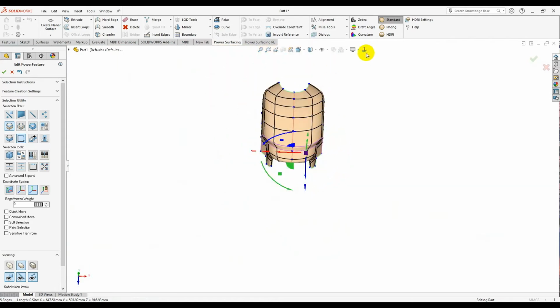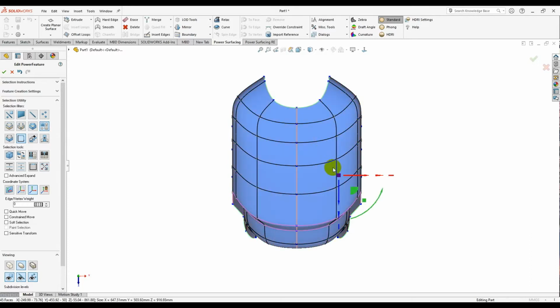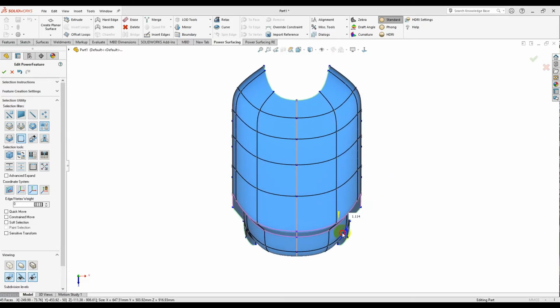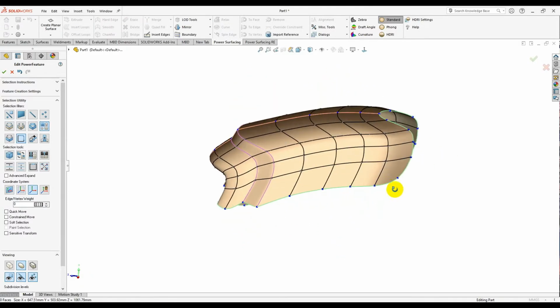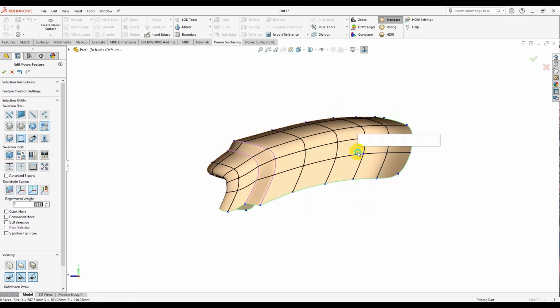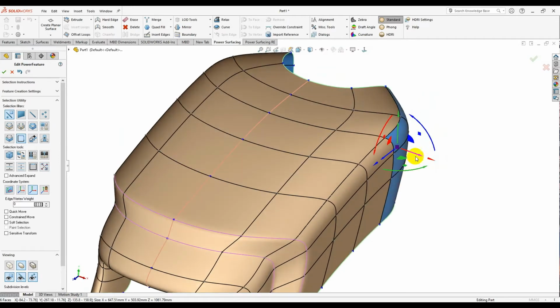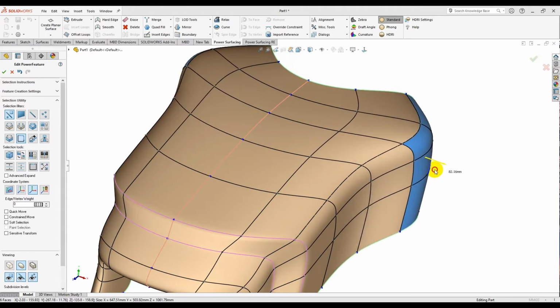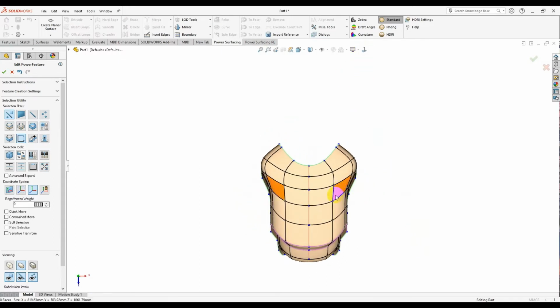Okay, now get the top view, using the whole shape by pressing switch to select element here and pressing on it. We can stretch it a little to give it a nice taller shape. Okay, like this. From here I can also easily select these faces and move them a little outside.